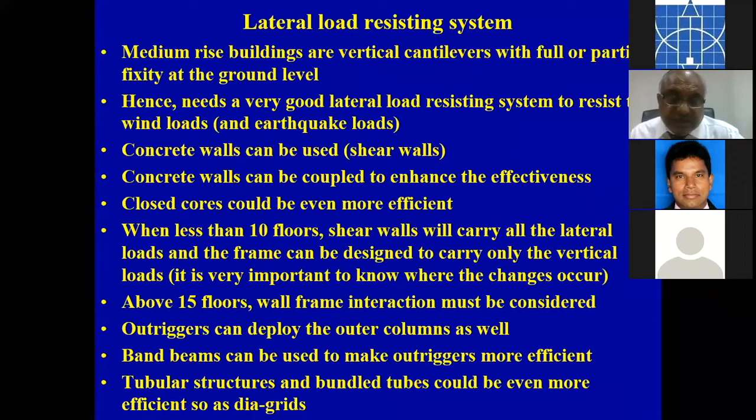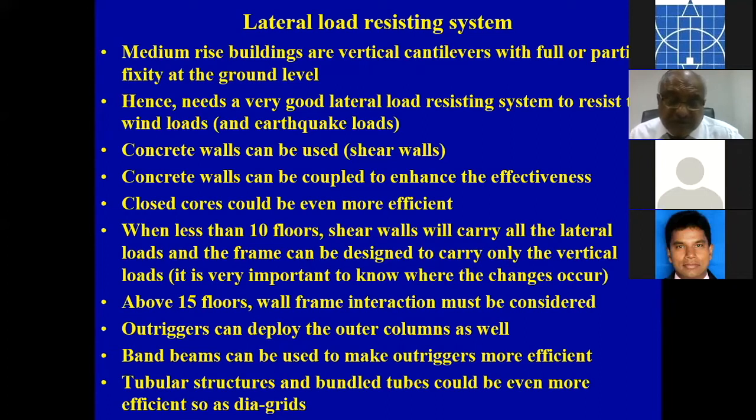The real reason is, it is a failure of a key element. Key elements are the elements that are actually holding the structure together, and failure of any of those structural elements can mean the total collapse of the structure. And one of the key elements that could have easily collapsed in that particular building was the transfer plate. Why? Because it's so easy to under-design the transfer plate, or you can have a transfer plate where you have the same factor of safety as any other beam in the structure, which is wrong. Transfer beams are so important. If you have the same factor of safety as any other beam, then you are making a big mistake.